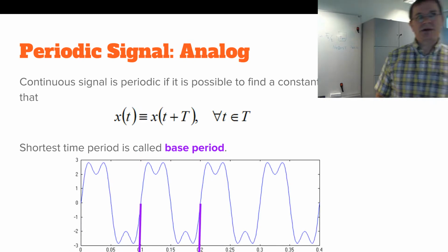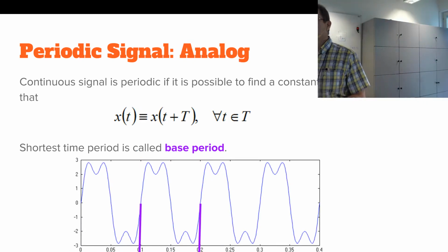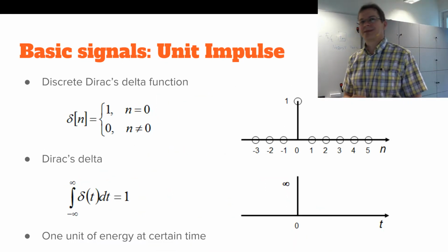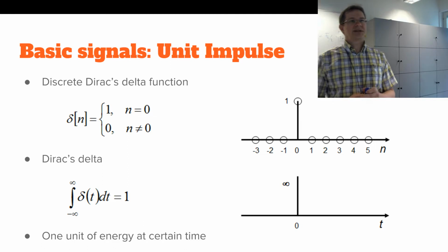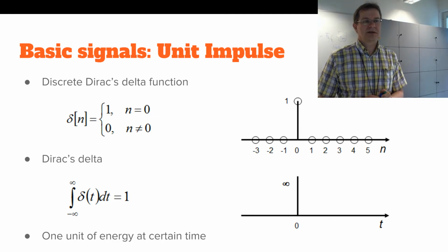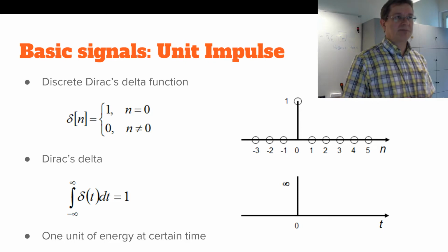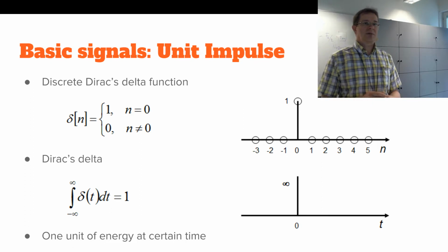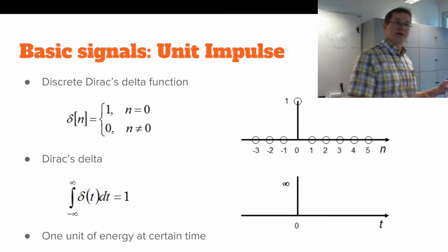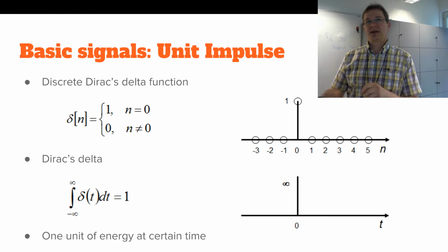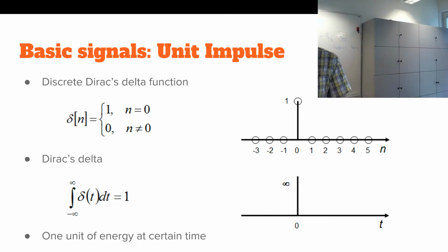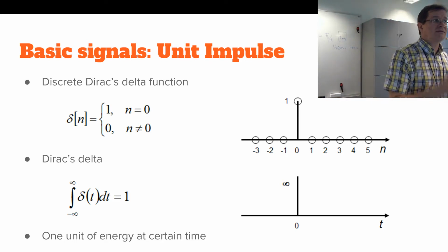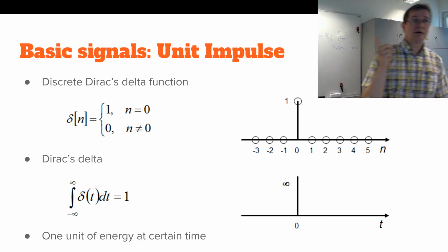So that was the unit impulse and unit step. Actually, the unit impulse is also the test vector for digital systems, since the impulse response function more or less defines how the system behaves. Basically you just take the unit impulse, run it through a system, then it gives you the impulse response, and that's everything you need if the system is a linear time invariant system.